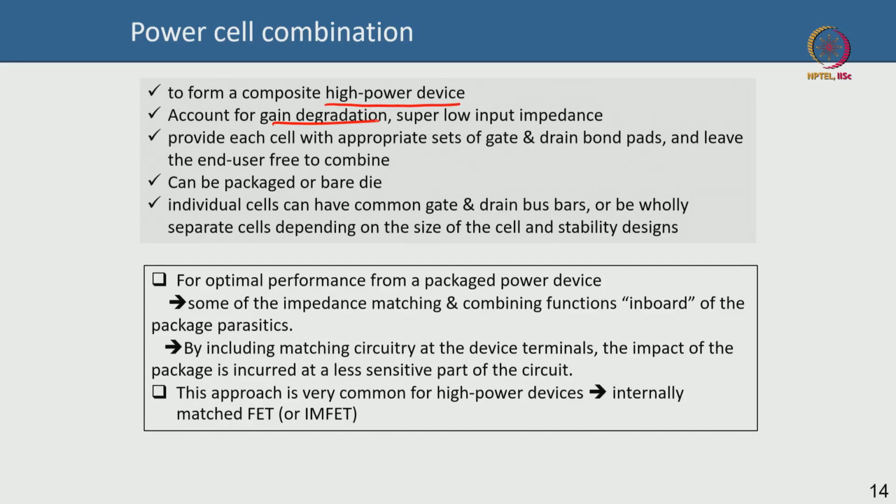I told you as the signal propagates it dephases, so the gain degrades a lot because of dephasing. The design has to take account of that, how you bring in the signal with wire bonds or via holes, which has to be really carefully designed. Most of these designs are not only device design but also design at the amplifier level with ADS simulation software, for instance. When you have large periphery devices you have very low input impedance. What does impedance mean? We will come to that towards the end of the course in microwave engineering. You always need to match the impedance.